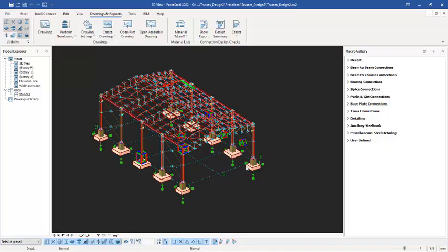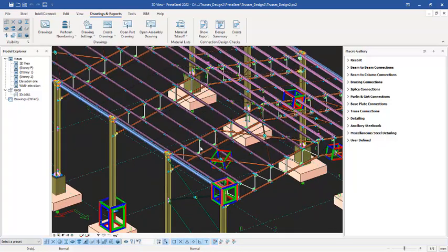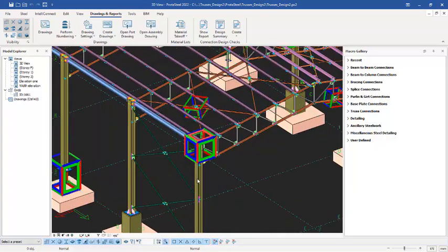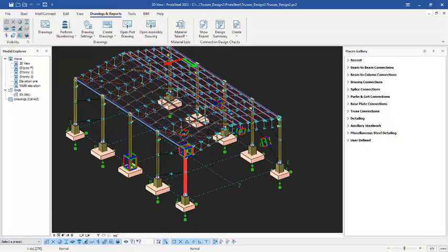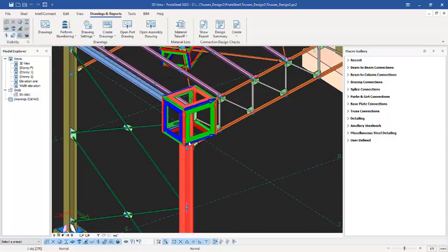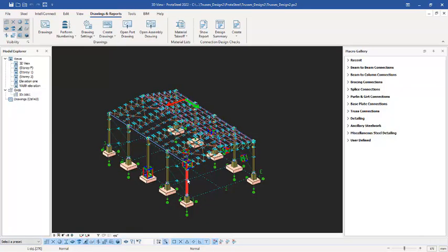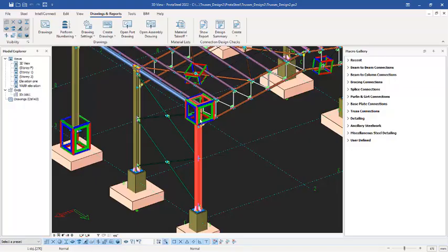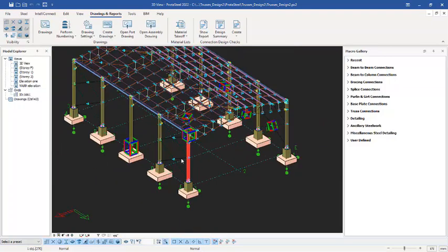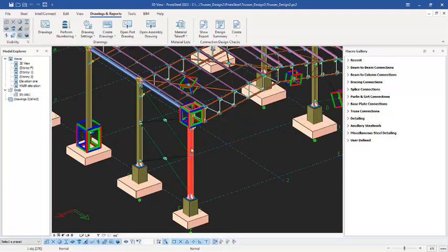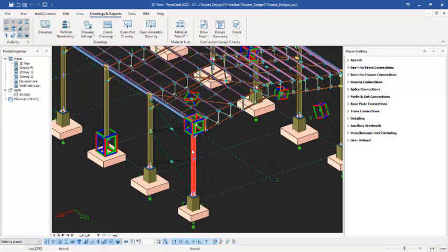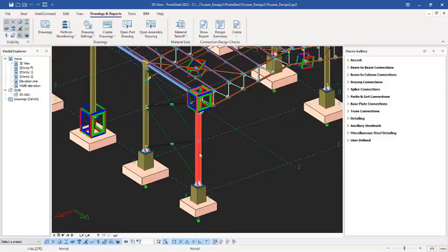But most of the times, if I want to create my own drawings, I wouldn't do it like that. I create drawings based on the members. I can just pick these members now and create an assembly drawing for this member, and I know that this type of member, I have it 1, 2, 3, 4. So any drawing result I have, I multiply by 4 to get the drawings for this particular member that is at the external edge of this structure.